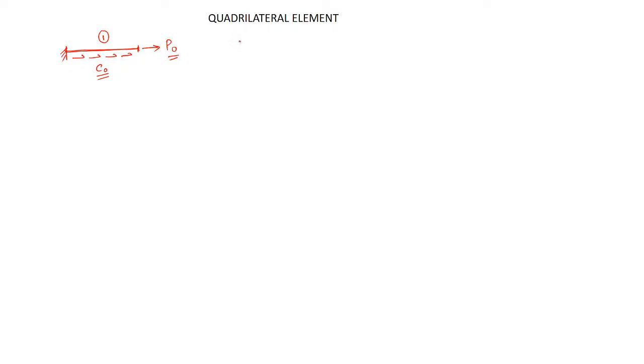And if you remember, the stiffness entry turned out to be, if I write this directly, EA integral of phi I comma x, phi j comma x dx. So integrate 0 to L. So I am assuming that the length of the bar is L. So if I follow that, I can find out the stiffness entry. So in that case, the stiffness matrix I will calculate.